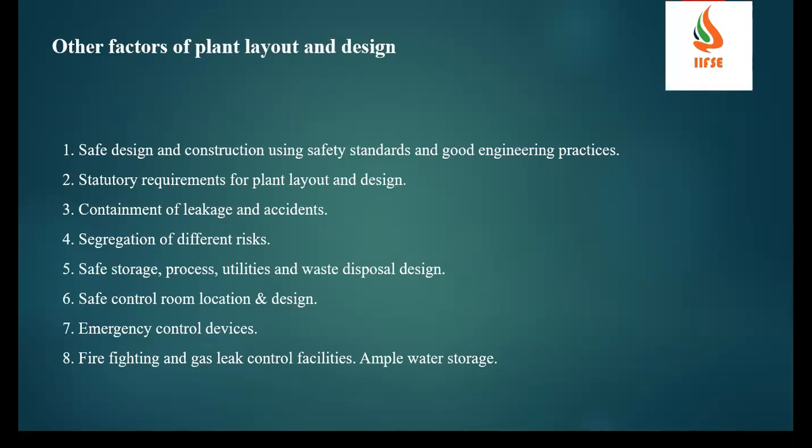So legal requirement: how much it will be, the staircase width should be this much, and if your building is more than 10 meters, a secondary set of windows needs to be provided. The door width should be this much, and also the first aid room should be this much size, and canteen facilities have to be provided for above 250 employees. The toilet space should be this much.